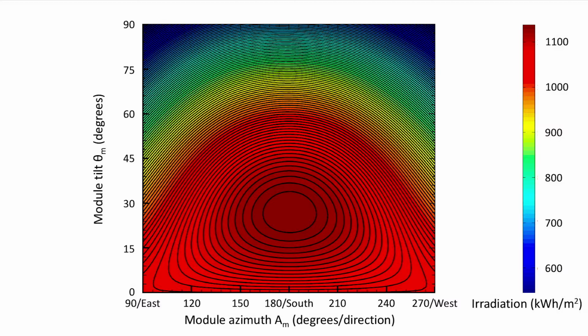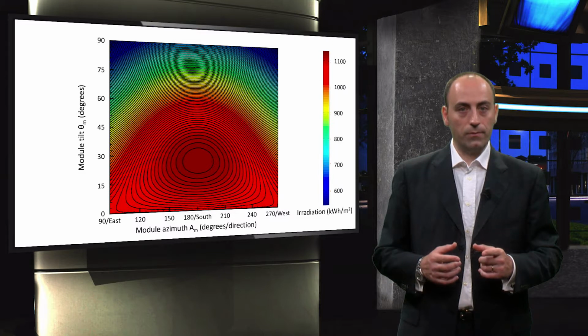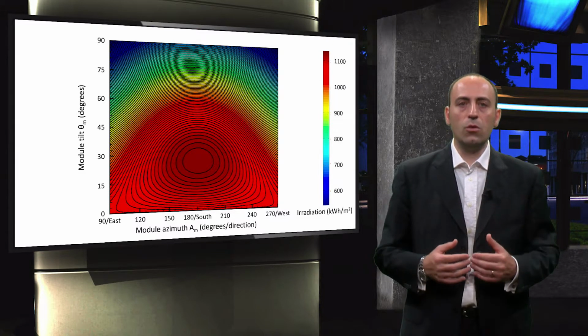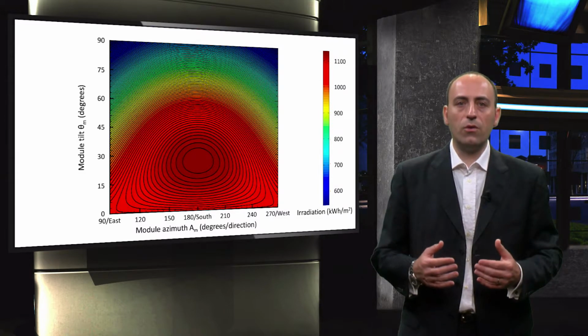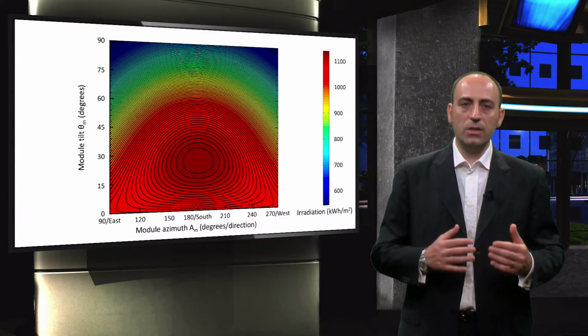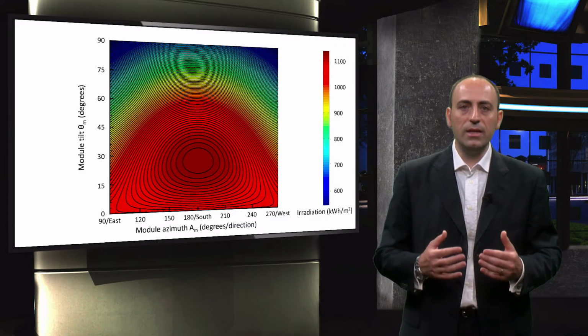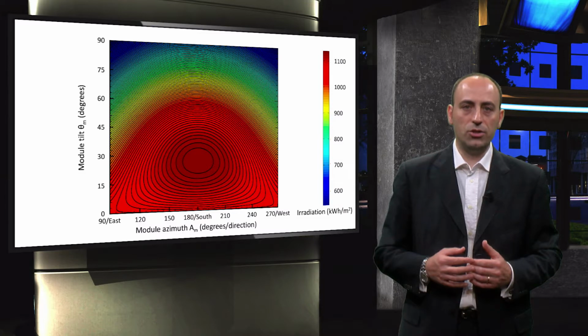The point where the incident energy is maximal corresponds to the best possible mounting configuration for the panels for that specific location. Note that in some installations, the array tilt angle or azimuth angle is decided for you. This can be the case for sloped roof mounted systems. Moreover, if your energy demand is highest in the winter, then you can optimize the tilt and azimuth for the winter months. This will, however, inevitably lead to a suboptimal annual energy yield.